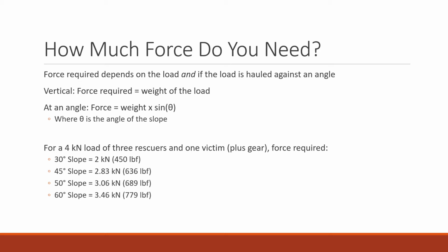So bust out your phone, your calculator, whatever, if you really want to do that math. We can kind of look at it in a general way. So we'll say that 4 kilonewton load of 3 rescuers, 1 victim with gear. What forces are going to be required? 30-degree slope, pretty gentle slope. It's only half as much. So you need 2 kilonewtons of force to move that 4 kilonewton load up the hill comfortably.